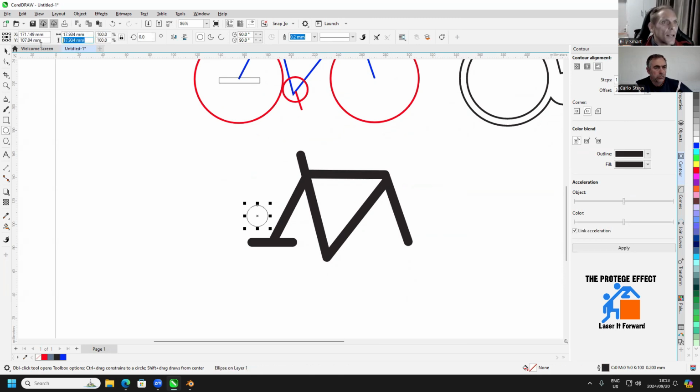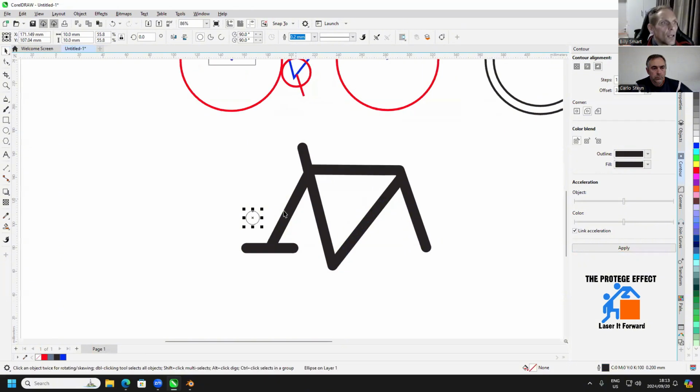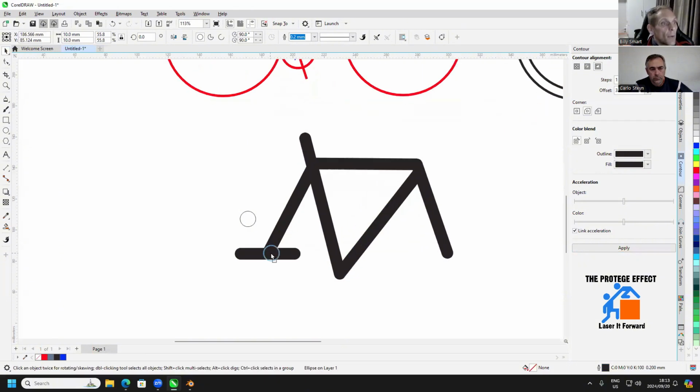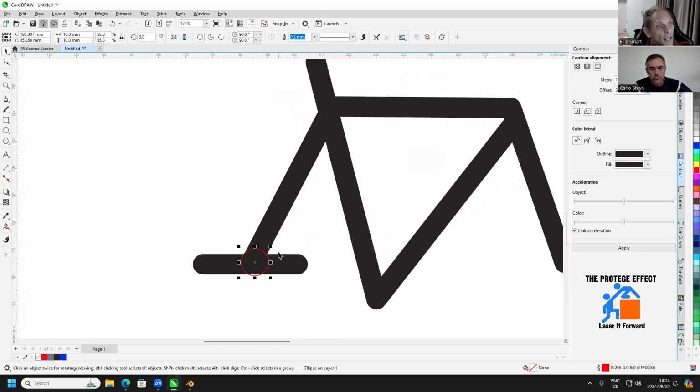From experience, I know that if I'm making a shaft or something on a model, I always make my center holes no smaller than 10 millimeters. How do I remember that? I've actually got a document, I think it's a six-page document, call me a liar, with all my standards and line colors and everything else that I use, and I try and stick to my own rules as much as possible.